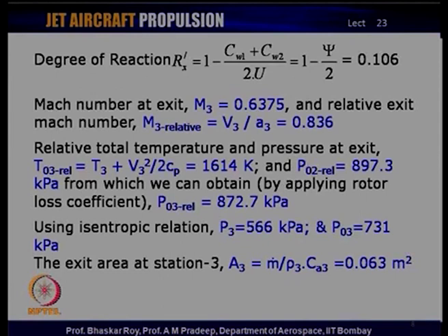Now, this is something you need to again very clearly understand, that the loss prescription that is normally given should be applied in the absolute scale in the stator nozzle and should be applied in the relative frame in the rotor, when you are calculating the pressure losses respectively across these two rows of blades. So, losses in the rotor take place in the relative frame, in the stator it takes place in the absolute frame. So, you need to take note of this and do your future problems accordingly.